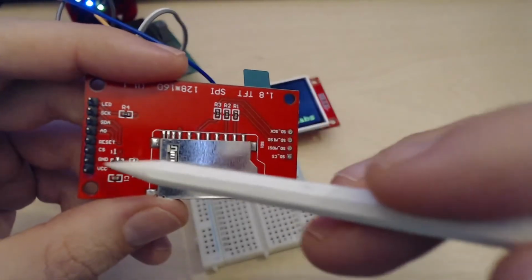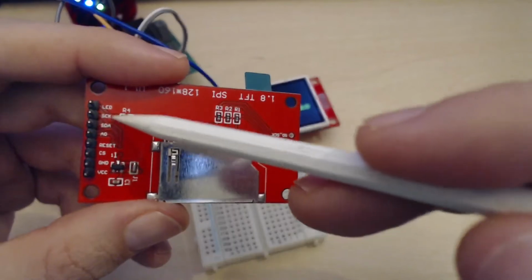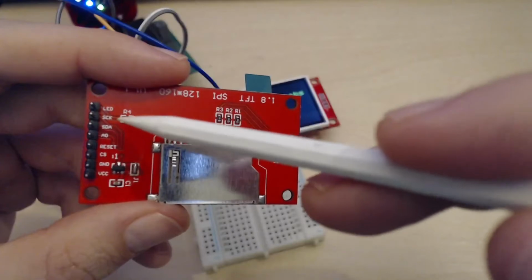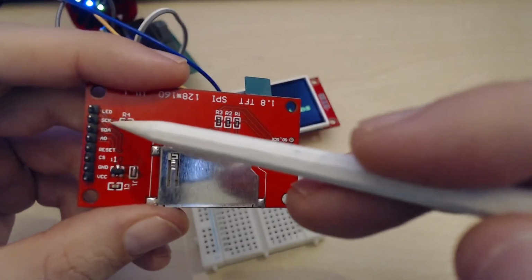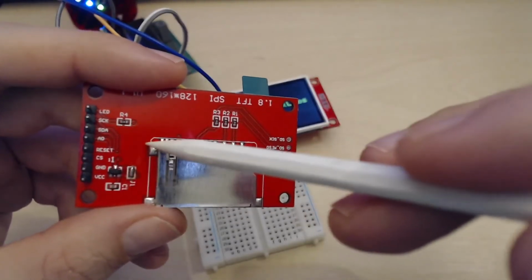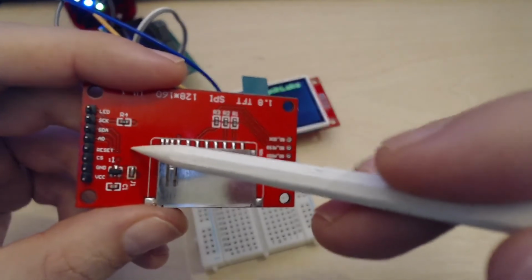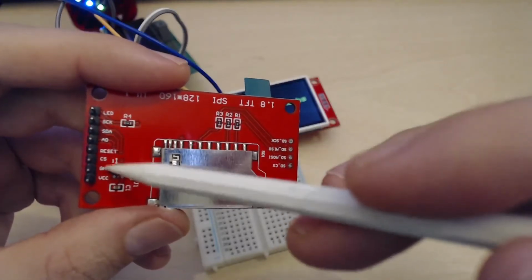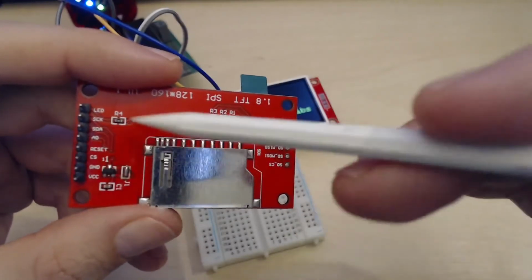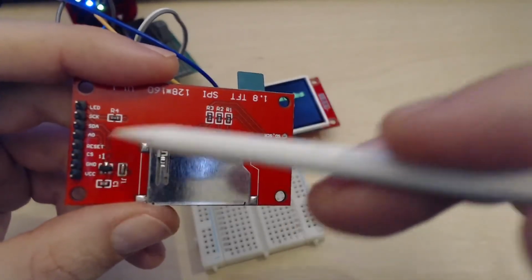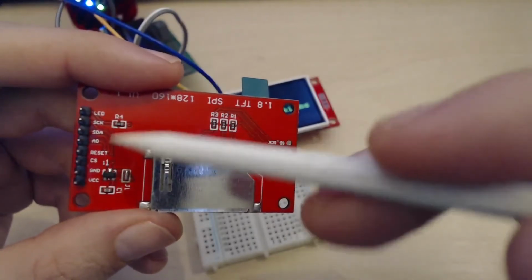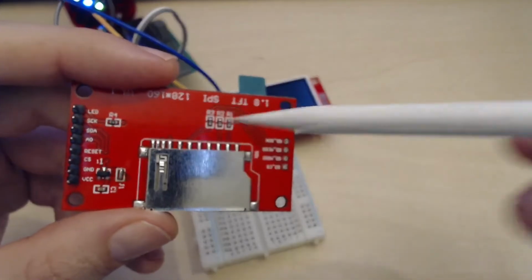So that's good, but it's not going to do anything for the pins, right? So if you are supplying your microcontroller with 5 volts, your microcontroller will be driving these pins at 5 volts, and that might damage the driver inside the LCD module. So you need to use a level shifter on these pins, and that's just a bit more components, right? So if you just drive everything with 3.3 volts, you don't need that. You don't even need to put any resistors, nothing at all here. It's just going to work.